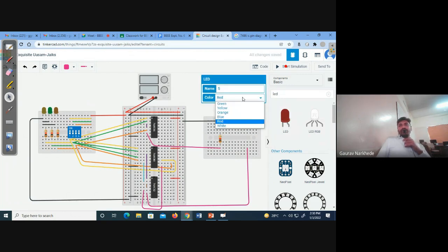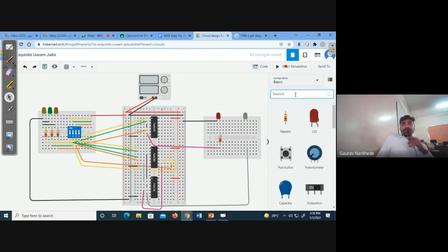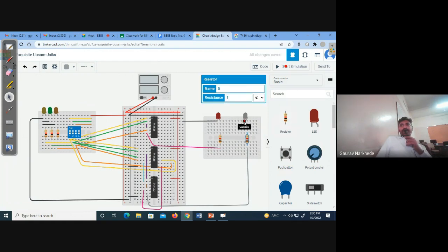And what color should we take for this LED? Maybe which color? White color is remaining, right? So this line we call gray, okay? And then this output is going to the LED through a current limiting resistor. Maybe I will put a resistor here, and the cathode is connected to, obviously this should be connected to ground. So this I am connecting to ground, okay.